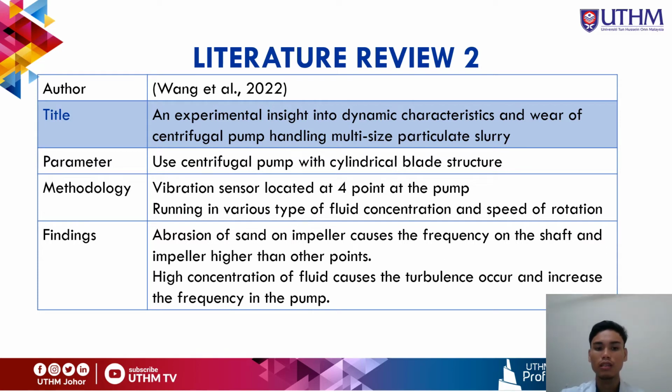The finding is that the abrasion of sand on the impeller can cause the frequency on the shaft and impeller to be higher than other parts, which shows the fluid in the pump affects the impeller and the shaft of the pumps. The higher concentration of fluid causes turbulence and increases the frequency in the pump. The frequency of the vibration may occur from the turbulence that is related to the concentration of the fluid.